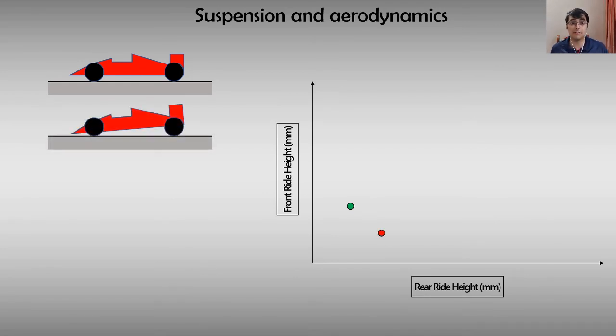Now the driver slams on the brake, the car pitches forward because it's moving, and as soon as you slam the brakes, it has a tendency to continue to move. So the center of mass of the car moves towards the front and it pushes the car downwards. Now at that point, the front ride height obviously dips and the rear raises slightly because of that. So the car will obviously roll about its roll center and effectively its roll center and the center of gravity. Again, we won't get into that here.